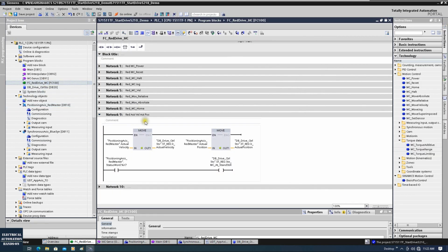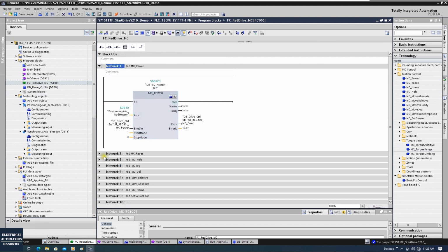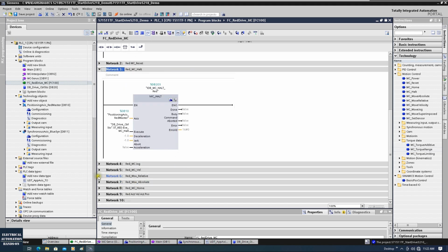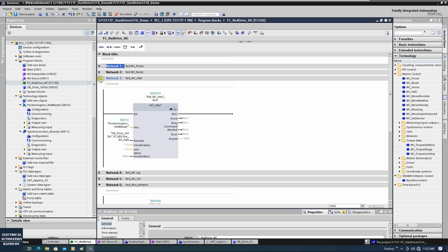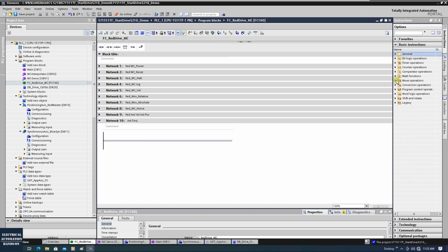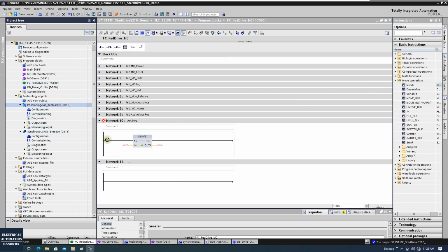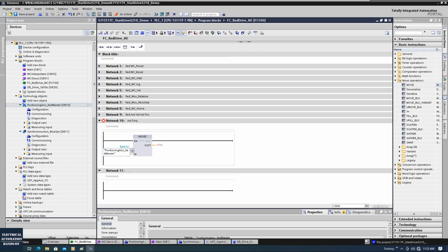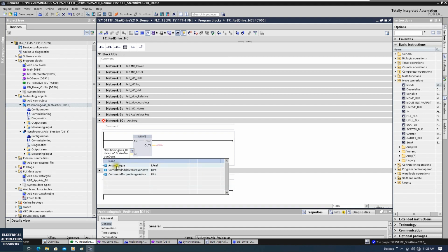In the previous video, I introduced how we can program the MC function blocks power, home, and relative move. And here I can add the reading torque and we can limit the torque. So firstly, I can program, we can read the actual torque value. Drag the move command. Okay, and drag this axis here, and then we can add this dot, find this status torque data, okay? And we can see this is the actual torque.